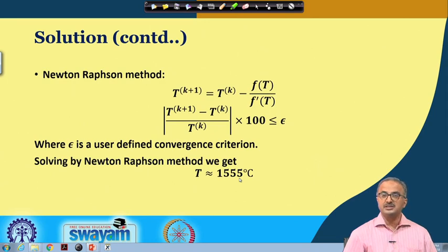So this is a pretty simple way of applying the energy balance, because in the energy balance we are assuming the change in kinetic energy and potential energy to be 0, adiabatic means Q is 0, and there is no work done because the reactor is a fixed, rigid reactor. So when we drop all those terms from the energy balance equation, we find that we are left with the terms which were shown in this particular solution.